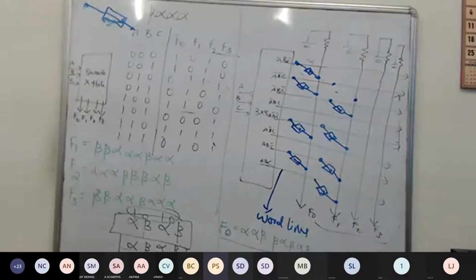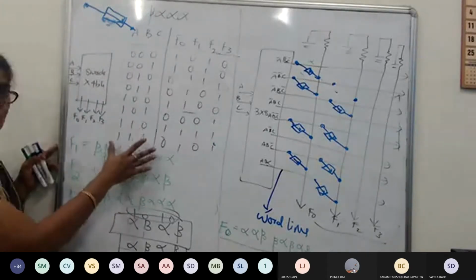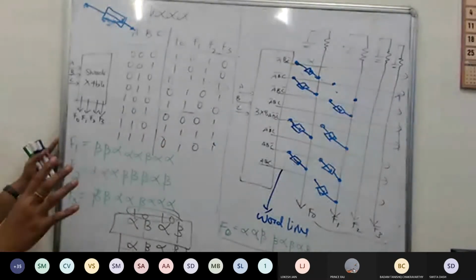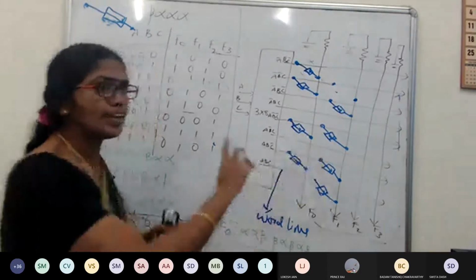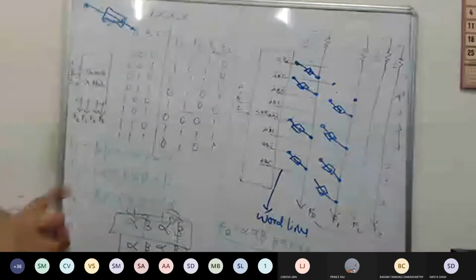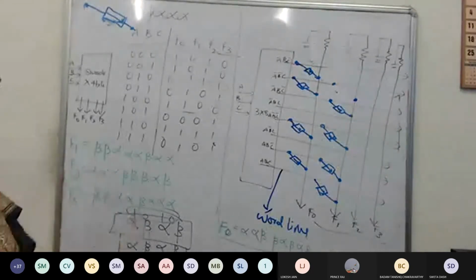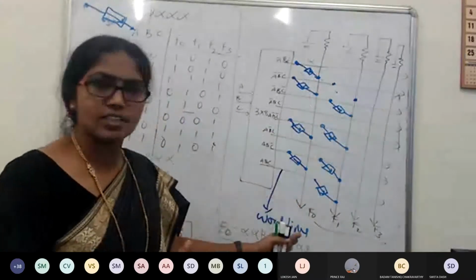Architecture, but I can make you at least get acquainted with how many programmable devices there are. Now, given this, we can prepare a mask. Why? Because we know that a ROM is nothing but a combination of a decoder and an electronic circuit where the switches can be made so that the word lines can be framed, and from the word lines the functions can be extracted.